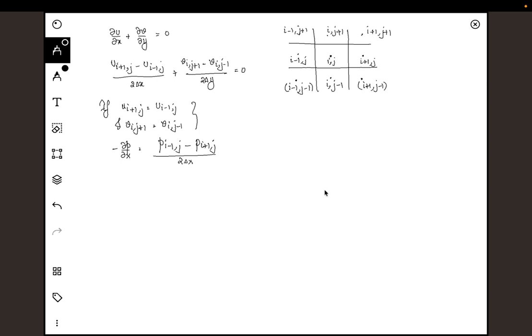So what could happen is, if I plot pressure as a function of x, at this point let it be 0, but at the next grid point it has a high value, the next grid point it has a 0, the next a higher value. So these are the grid points. What if pressure is oscillating like this in space? Obviously, from a physical point of view, this cannot happen. If this happens, then the derivative should not be equal to 0.